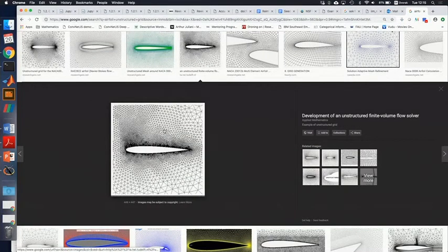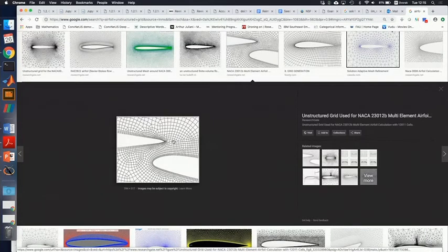So with these unstructured grids, keeping track of i equal something, j equal something becomes much more cumbersome. It becomes almost impossible, especially when you have different sizes of cells. So in that situation, you would keep track of who is my neighbor, and I will do all my finite difference by talking to my neighbors.